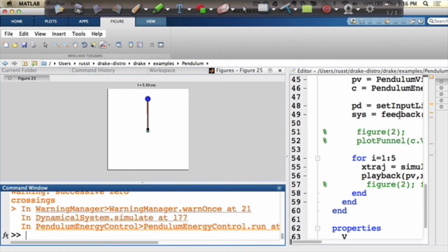Yeah, I think that would be the number one problem, especially since the LQR controller is not necessarily good at thinking about all the wrapping issues. The nonlinear controller, just by having the sines and cosines inside the equations, actually handles all the wrapping of the coordinates very nicely. So I think that's probably the number one reason. But you're right, the complexity of switching is this extra logic of being a switched system that we'll talk more about later. And that's a pain.